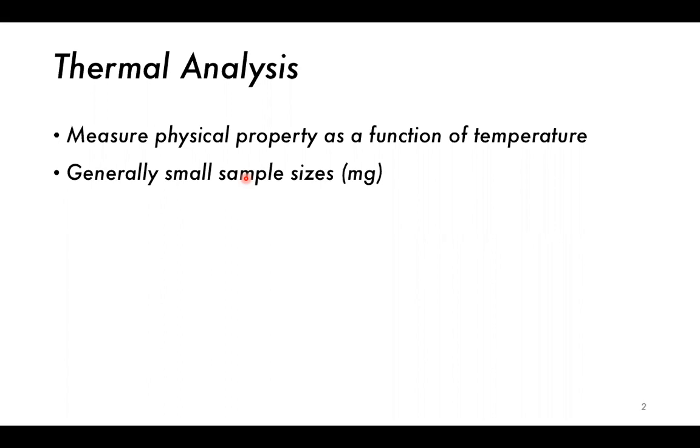It's not crystalline in nature. Crystalline basically means that there's some sort of repeating structure throughout the entire material. So it goes A, B, C, A, B, C, A, B, C, and so on. But in amorphous, it may go A, B, C, B, A, something like that, where A, B, and C are just different ways of arranging the molecules.